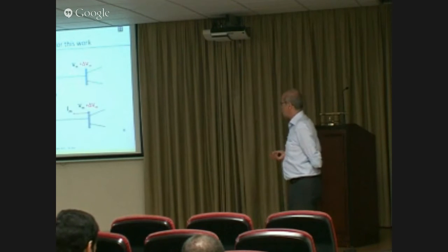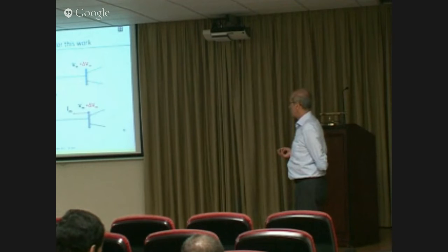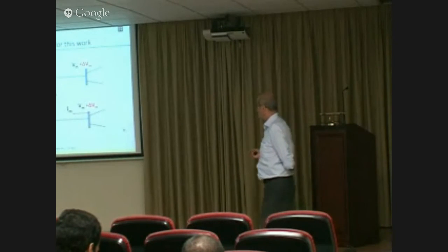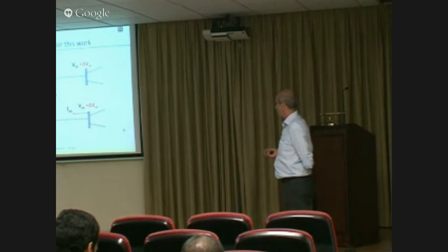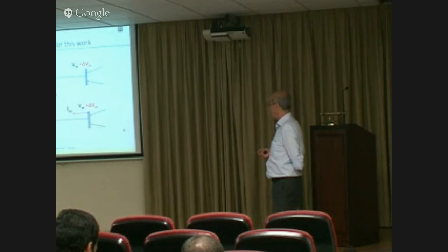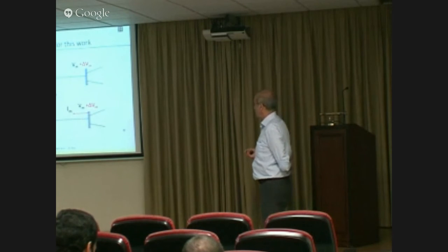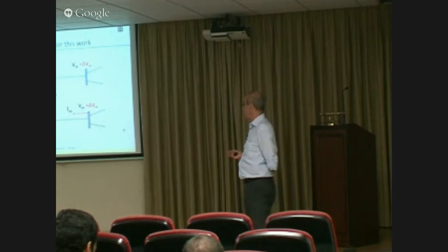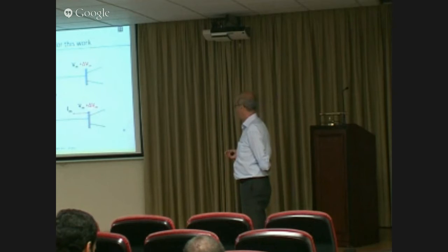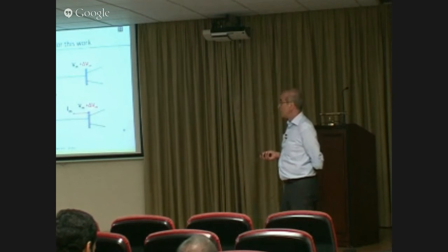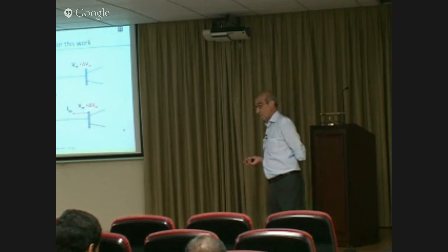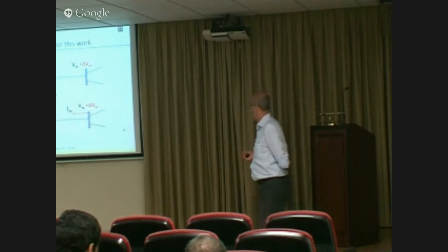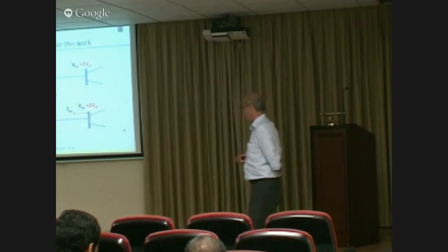Now, you can show that instead of applying a fault and injecting a current here, you can do similarly what we did for the line outage. You can use two injections, one here, another there, so that these two injections will give you the same voltage changes. So you get the same voltage change here and there, but instead of using a single IF, you use two injections at the two ends. So the nice thing here is, even though we don't know where the fault is, we know the terminal, so we know exactly where to inject these currents.